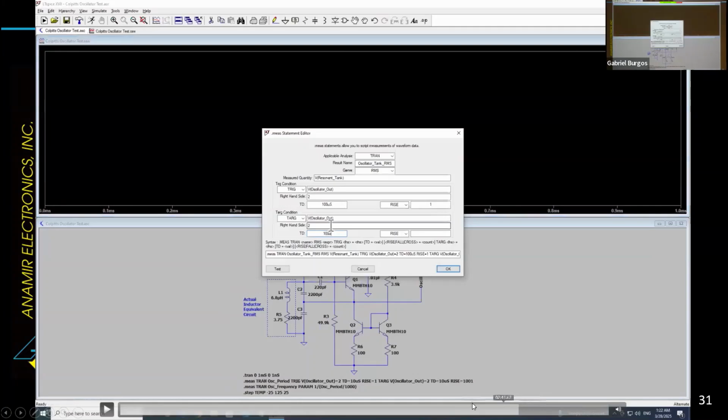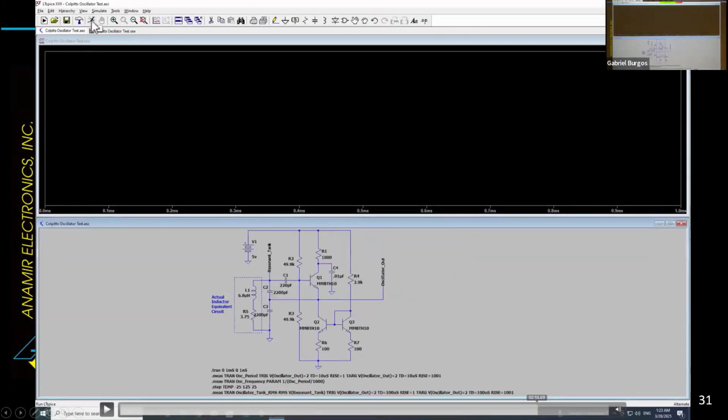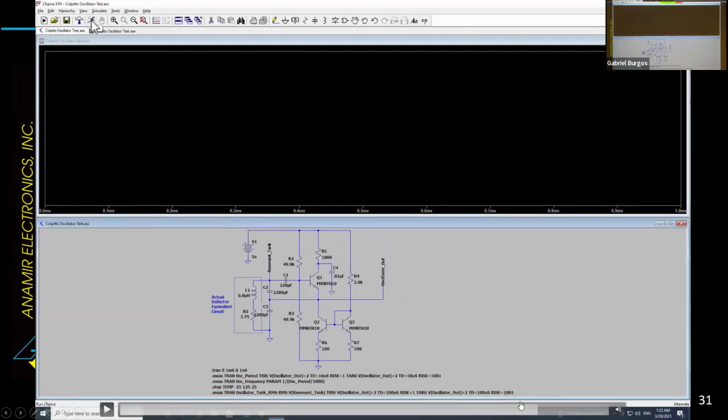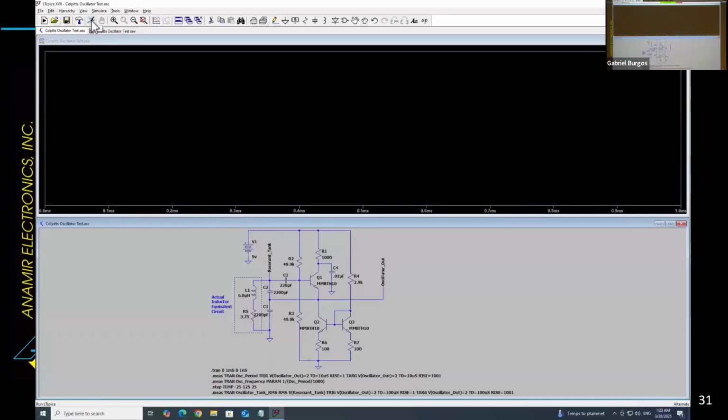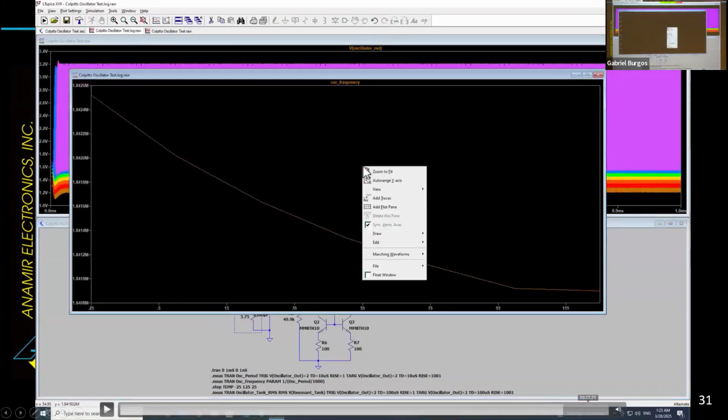Anyway, in LTSpice, you can very accurately measure the frequency. It's very nice. You just have to set up measure commands, and you can set up a measure command to pick off a certain voltage on the sine wave, and then have LTSpice actually count how many times the signal passes that threshold, and then you can report that. You can even do a little math to get the kind of units that you really want.